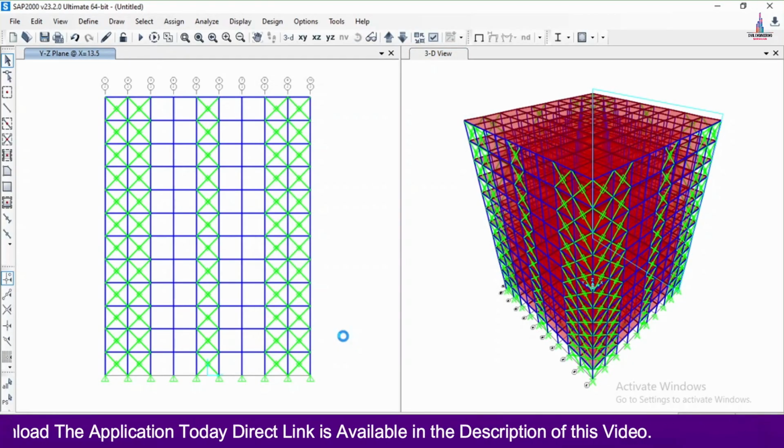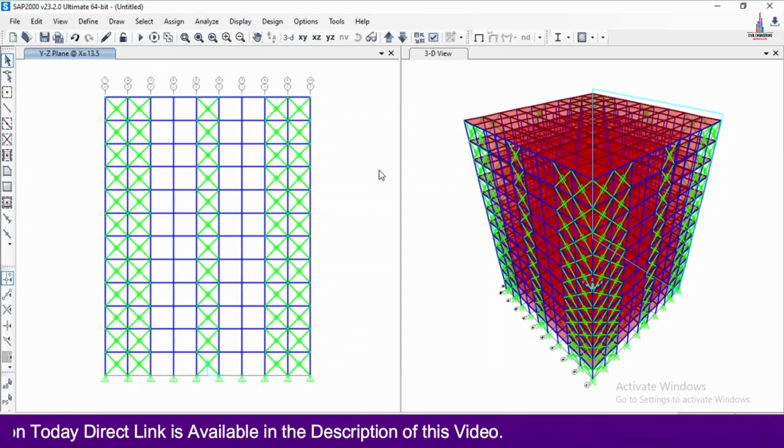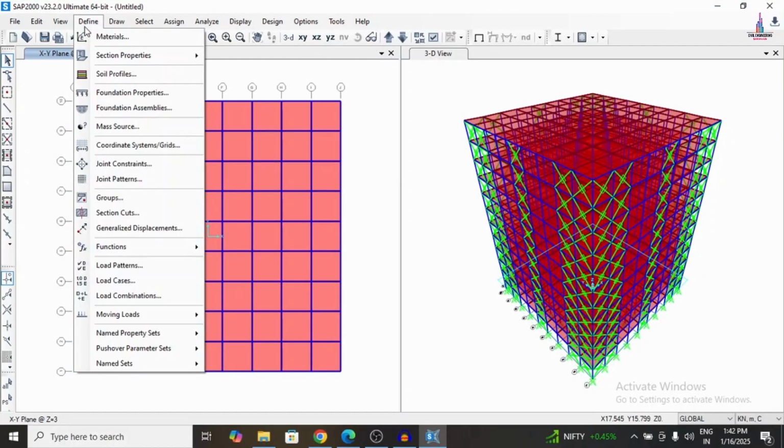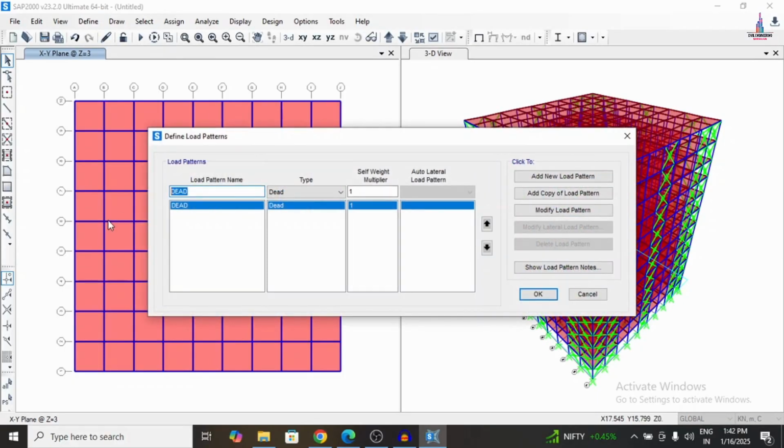So now after defining and applying the dampers, we need to apply the load cases according to our assumed data. So now here initially I am defining the load cases. Go to load patterns option. So here it was done with the dead load. Here we have to select the live load condition. Just I am selecting here as live.